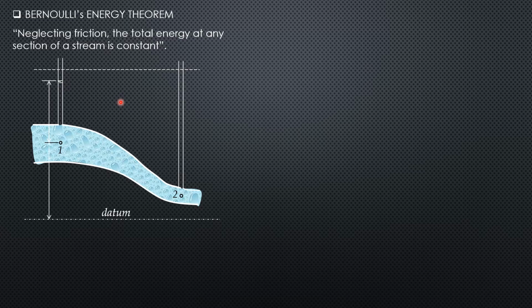So these are the forms of energy. We have Z1 here. Because of pressure, the liquid will have to rise to this level here, wherein it is imagined to be in exposure to the atmosphere. So it will rise because of pressure. That distance from 1 to that liquid level is the pressure head. So this is elevation head, pressure head at 1. And because there is velocity at 1, then this is the velocity head, v1 squared over 2g.